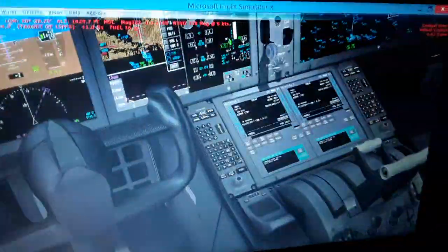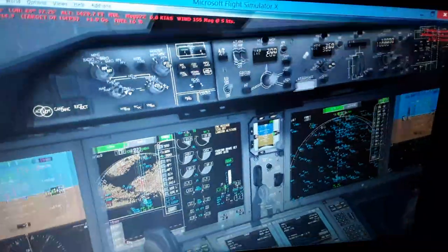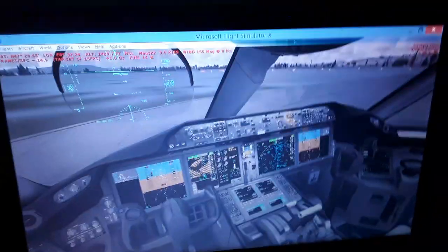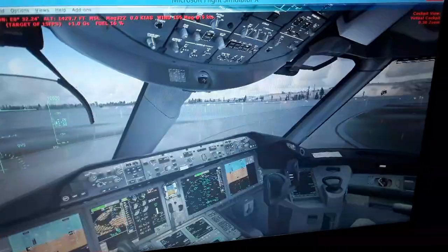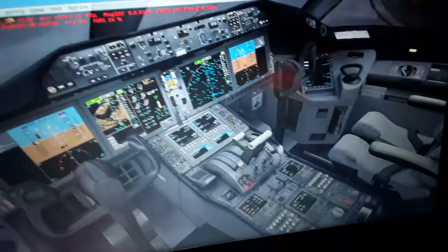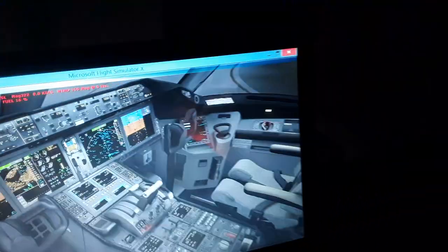Also, as we descend, we need a different fuel mixture. Also, they recirculate the fuel from the fuel tanks, the left and the right wing and the center tank, into the engine components to heat up the fuel from the engine's heat, and also duct heat from the engines. And also we do the same for the oil and the lubricant, right? So we have many sensors from the FADEC. So this is a small explanation about the FADEC control.